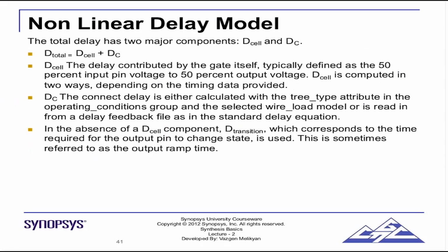Now let's look into NLDM, the non-linear delay model. It's a very interesting concept. The linear delay model suffers from some shortcomings. It is not accurate enough to represent present nanometer technology. Even 90 nanometer is not good enough. So it is replaced by non-linear, because the linear delay model, as the name suggests, says the delay at the output will vary linearly if the input changes, and that is not the case. It is not a straight line.